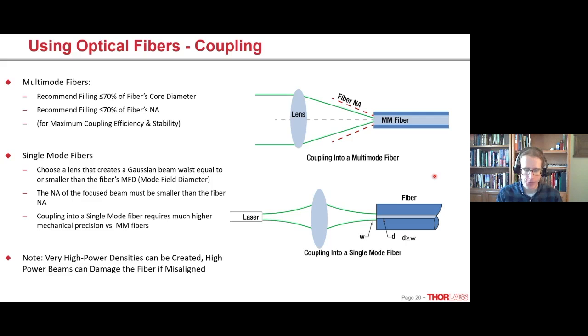Yeah, there's a couple different strategies for looking for breaks in fibers. And it sometimes comes down to, is the fiber already installed in a data center, in an application, or do you have access to the fiber? The most basic way to do it is with what we'd call a fault checking light source. And it's as simple as it sounds. Visible laser or visible LED coupled into the fiber, and then inspect along the fiber's length. And if you see a bright spot, that means light's leaking out, which means something is wrong with the fiber. Not just a break, but also maybe some sort of internal defect in the fiber. Things like that. Not that those come up very often, but it is possible.